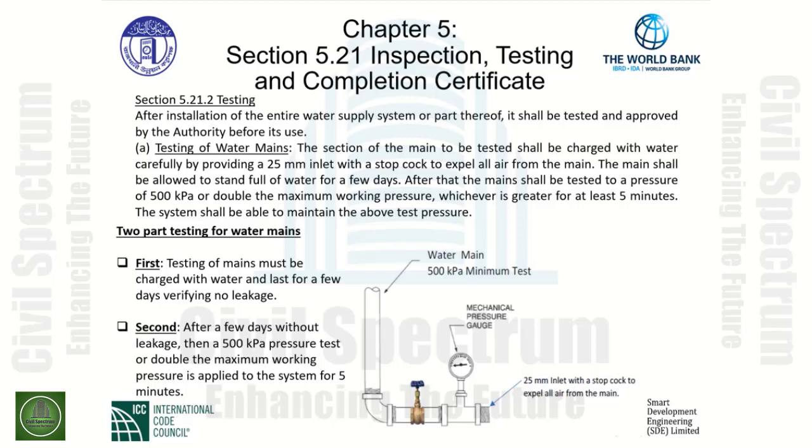In other words, we are charging the entire main with water at a static pressure. The main shall be allowed to stand for a few days full of water. We observe at that point to see if there is any leaks in the system.